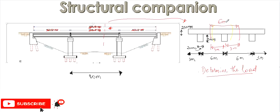Now, it is given that the slab has a thickness of 250 millimeters, and the size of this beam is the same as this one and this one. It has a depth of 300 millimeters and a width of 200 millimeters. It is the same. So first we have to determine the loads coming from the slab.